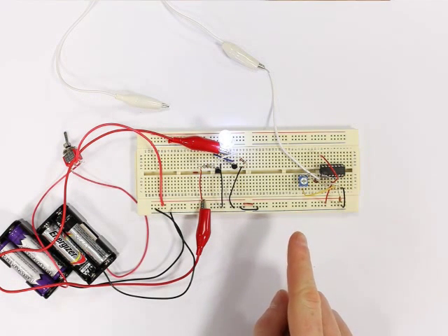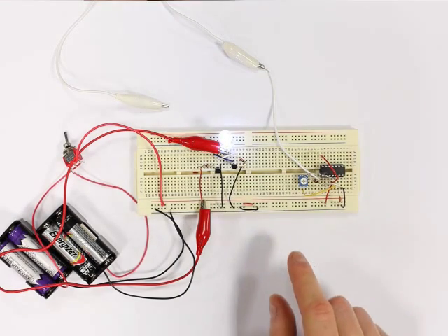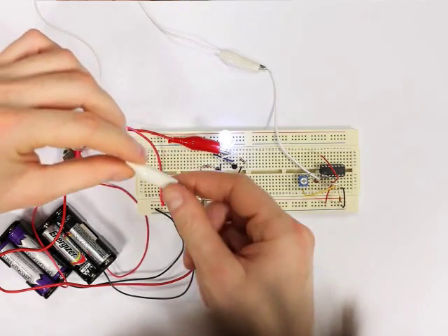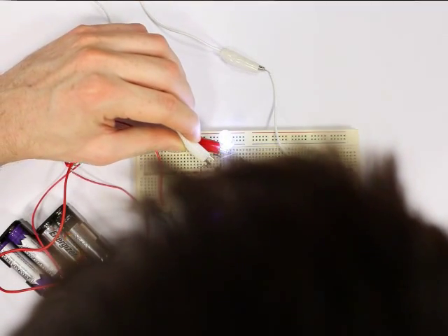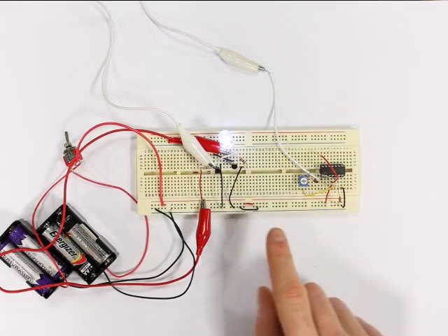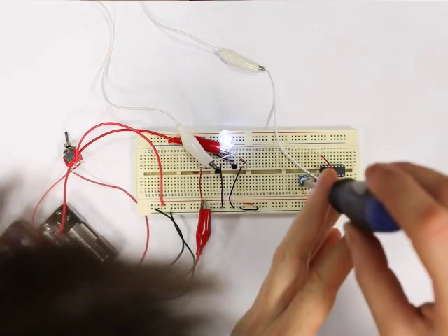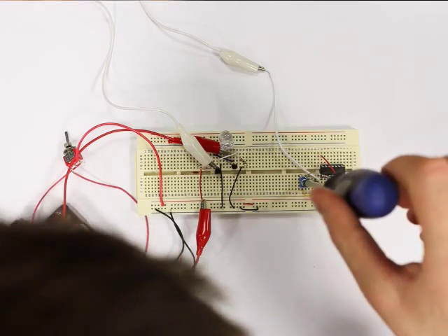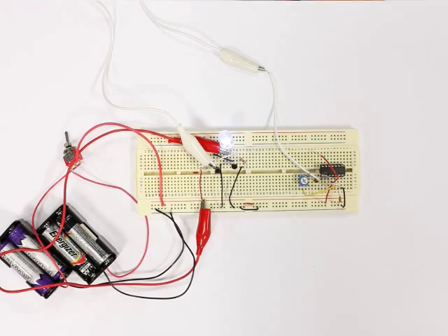Now I haven't actually connected the PWM circuit yet, so that's just the LED running on our previous constant current driver. But this is the pull-down connection, and I think I'll just attach it to the leg of the gate resistor there, which of course is connected to the gate. And there we go. We saw an instantaneous drop in intensity when I connected that. And I should be able to further adjust the intensity using the trim pot here. There we go. I can almost completely turn it off. So that's looking pretty good.